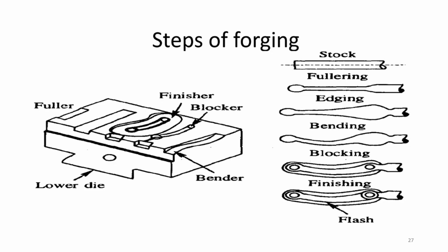For that particular part, you take that into consideration with the help of pattern allowance. That is solid shrinkage. And after that, liquid shrinkage means some part starts to solidify earlier, so as the shrinkage occurs in between, that part of the casting is filled with the molten metal that is in the riser.